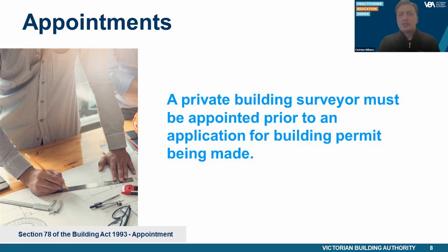Only an owner or their agent may appoint a private building surveyor. It is important to note that where the work is domestic building work, the builder cannot appoint the building surveyor. This applies even where the builder has been authorised by the owner to act as an agent on their behalf for the application.